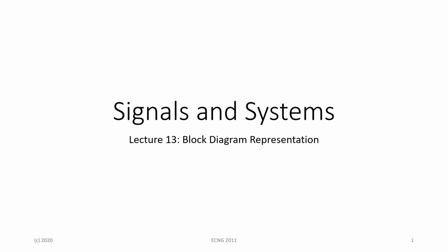Alright. Okay, so today's lecture is going to be focusing on how we represent our mathematical differential equations as visual block diagrams themselves, as well as how we manipulate these block diagrams or resolve them back into a transfer function equation in particular. And what you'll observe in today's lecture is that we actually follow the flow of the signals throughout the block diagram to obtain our transfer function equation.